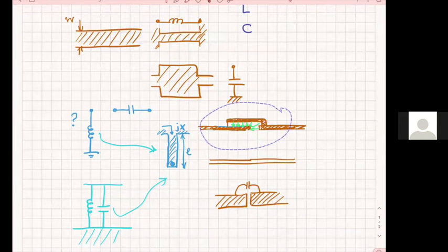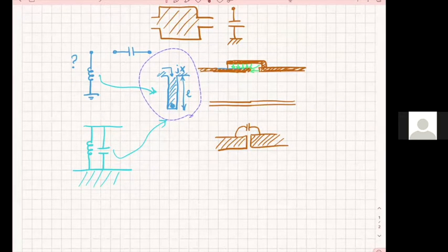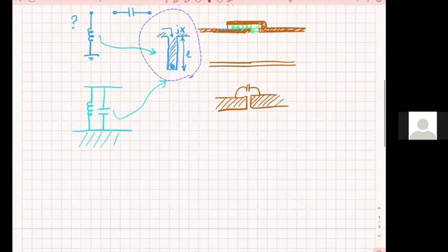All of these approximations will not necessarily in reality affect your pass band, but if you were able to go to software like HFSS, that can very accurately characterize all of your microstrip geometries, you will see variations, especially as you approach the cutoff frequencies, and then you go outside of your band. But in any case, in the pass band, I think you're going to have a good approximation of your design.